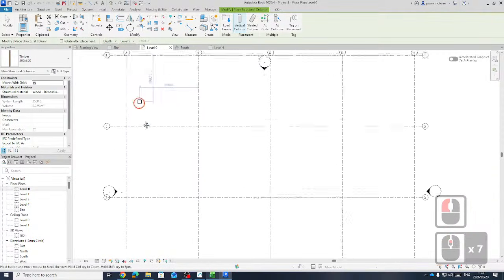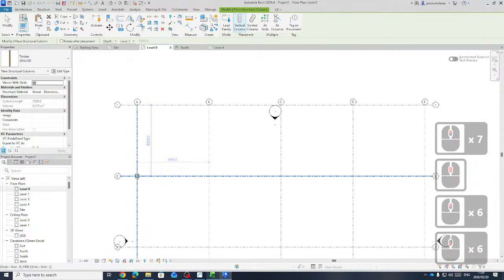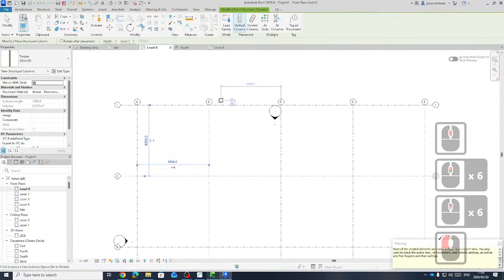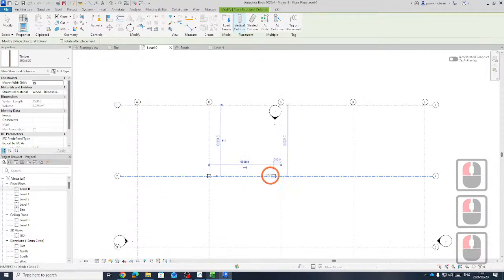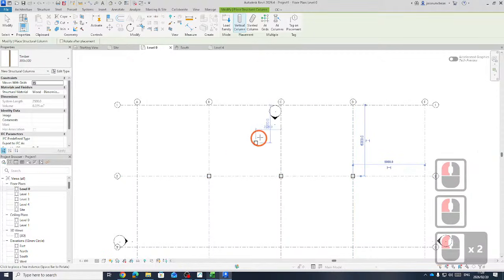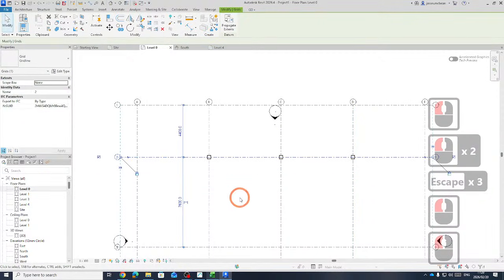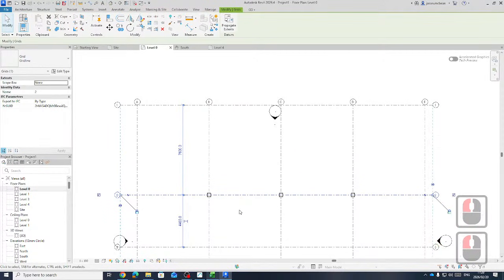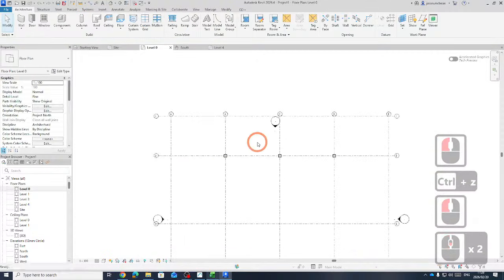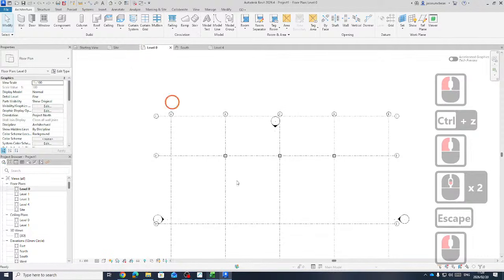Now this is also very unique about Revit. As soon as you click on a column, it's supposed to be level height. My apologies. I'll fix it very quickly. So as you drop these in and I move the grid, okay, the downside to Revit and its power as well is trying to create these relationships the whole time. You're not knowing this. So you might delete a grid. It deletes all the columns. Okay, so just understand that in Revit there's a bit of a complication in that sense.